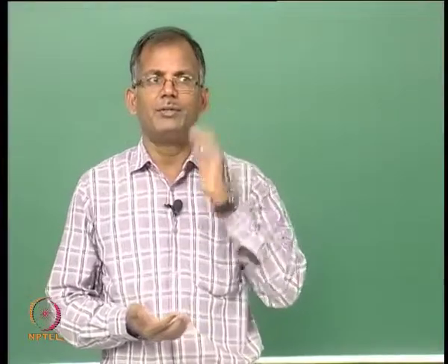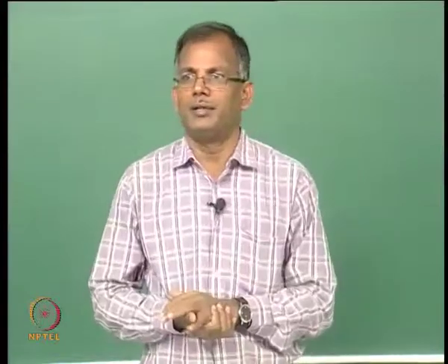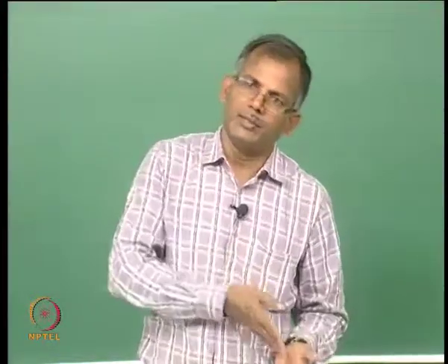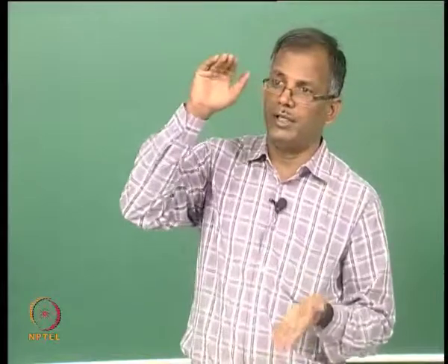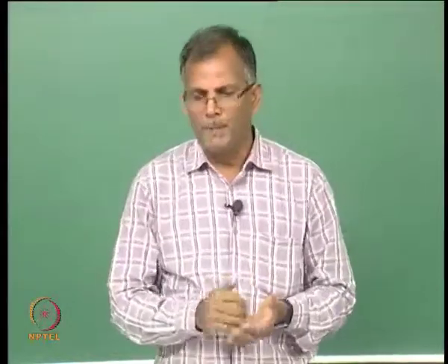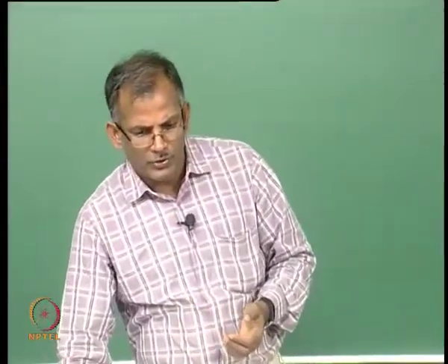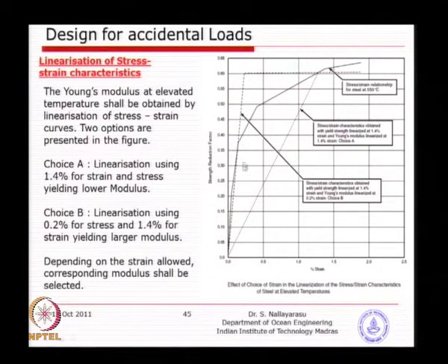If you have a typical linear elastic, bilinear stress strain diagram, then it is very easy, because you will take the initial slope, because most of your design is going to be within the 0.2%. You see here the first point is of course 0.2, but even before that there was a slight kink, maybe at 0.5%. So, it is continuously changing, and we need to find out what will be the best assumption or approximation we can make, as we discussed yesterday.